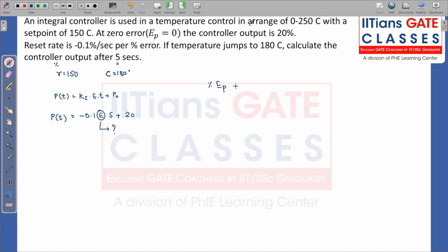We know that percentage of error in controller is given by the formula R minus C divided by C max minus C min, into 100. R over here is 150, C is 180, and C max minus C min is 250. So this is minus 30 by 250 into 100. The zeros cancel, and this gives minus 12%.